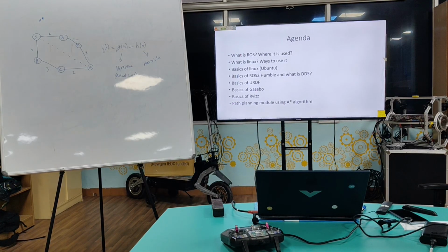Have you guys heard about lidar? It will give you a mapping around your system, right? So I'm using a 2D lidar, and this lidar will help me to recognize what is around my system, and I use this as well as my camera for object detection and path planning, lane detection basically.